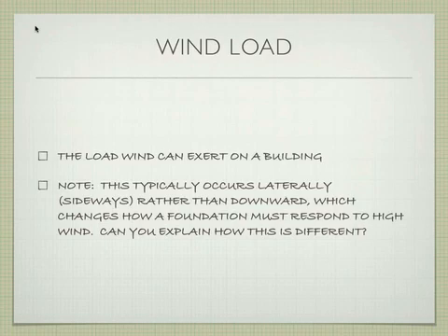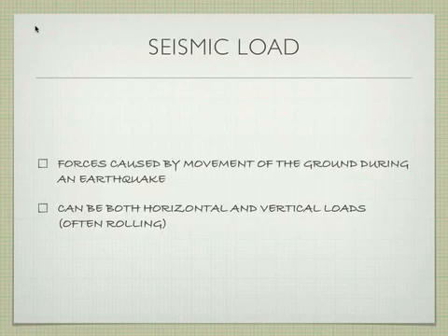And if the wind is pressing from the side, it's going to want to blow the house off the foundation. So you have to think of wind load as not being a vertical force, but a lateral force pushing to the side. So how the foundation handles that force is very different than how it handles the vertical load.